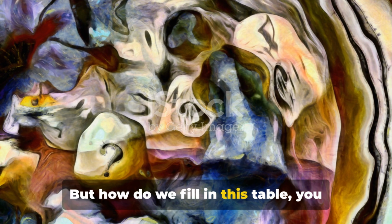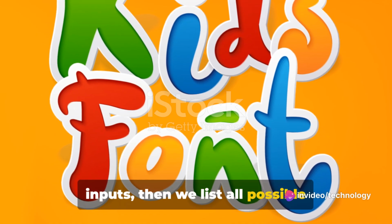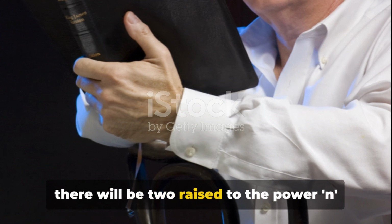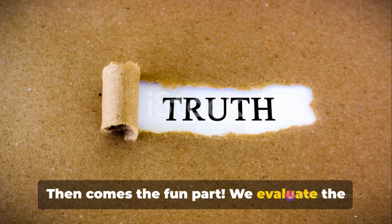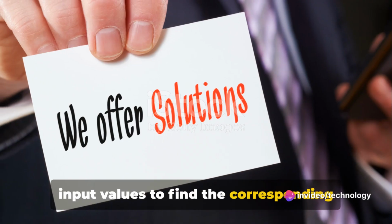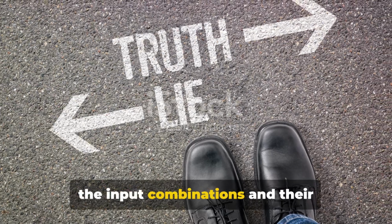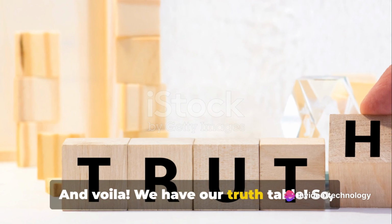But how do we fill in this table, you wonder? First, we determine the number of inputs, then we list all possible combinations of zeros and ones for these input variables. Remember, for every n input variables, there will be 2 raised to the power n rows in the truth table. Then comes the fun part. We evaluate the Boolean expression for each combination of input values to find the corresponding output value. It's like solving a puzzle, isn't it? Finally, we fill in the truth table with the input combinations and their corresponding output values. And voila! We have our truth table.